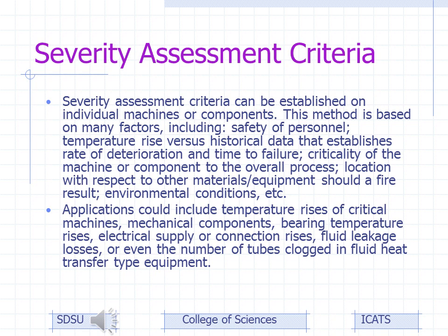So if this piece fails, what will be the result? What else will go wrong? We found a piece that was both the incoming and outgoing control panels for a machine, rather an engine space on a ship, that were hot, and if one went, it would have taken out the other one. You would have had a fire in a relatively small space, an engine room on a ship, and you would have had no ventilation. One box would have caught fire and burned the other box. So by the time the fire people got there, they would have had no ventilation. That would have been rather important to saving the ship itself.